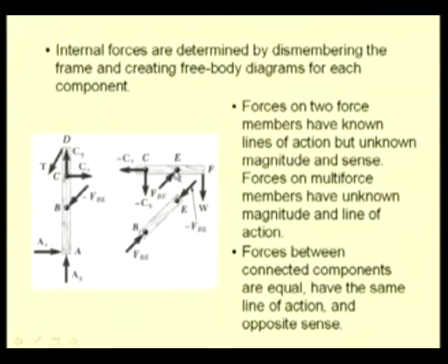So, when dismembering, we associate a pin with one of the members, because at E this member CEF and the member BE are connected by a pin at E. The pin at E is assumed to be associated either with this multi-force member CEF or with the two-force member BE. Always while solving, we start from a multi-force member and proceed.